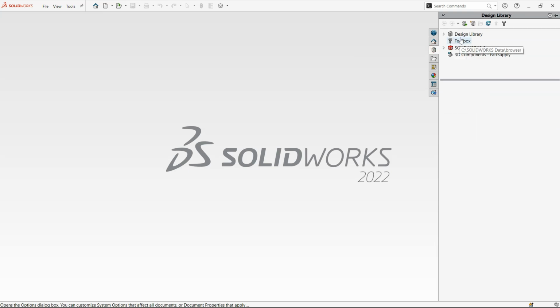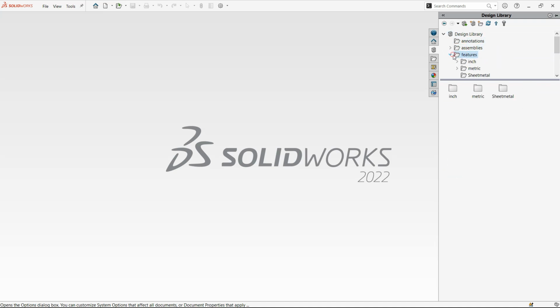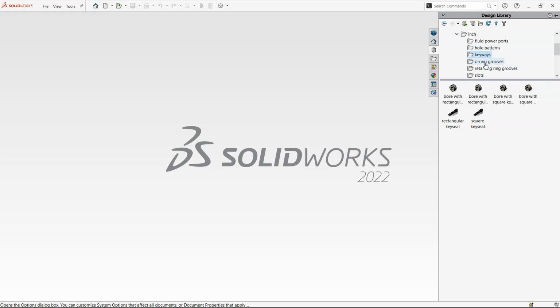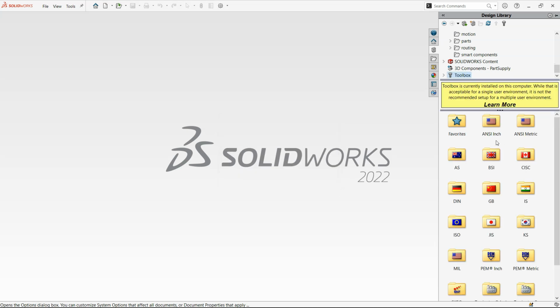the design library section. In the design library we have parts which are designed by default. So annotation, assemblies, features. In features we have inches, fluid power, hole patterns. We see there is a circular pattern and a linear hole pattern. We have keyways, we have rings, we have slots. In the metric section, you can see that all the parts will be in mm. And the forming tools, as you know, are used in sheet metals. We have embosses, flanges, ribs, louvers, etc. These are basically designed and provided when we download the options here.